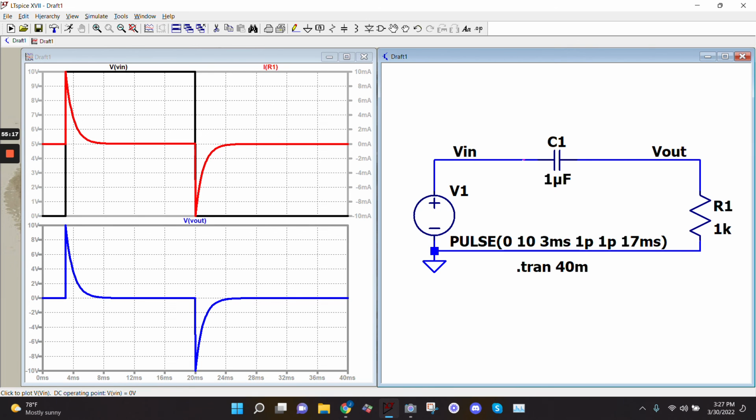Yeah, I was going to ask this. I think the answer is no, but would you use a capacitor in a light dimming system, where you dim the light and increase the light? You can. But this would not be a very good idea, because you won't be able to control the dimming. It will just dim at RC times 5. It's not going to be a controllable dimmer, basically. So you'd turn your light on, it would get bright, and then it would just get dim again.